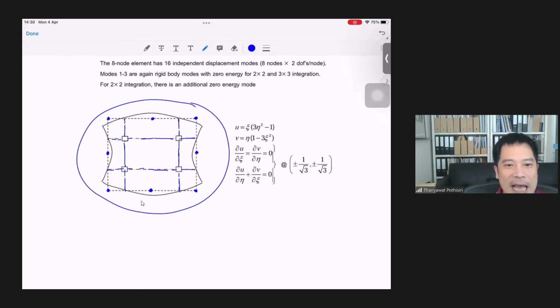So that means that when you perform the finite element computation, instead of computing your element stiffness matrix by using analytical integration, you're going to use numerical integration instead.